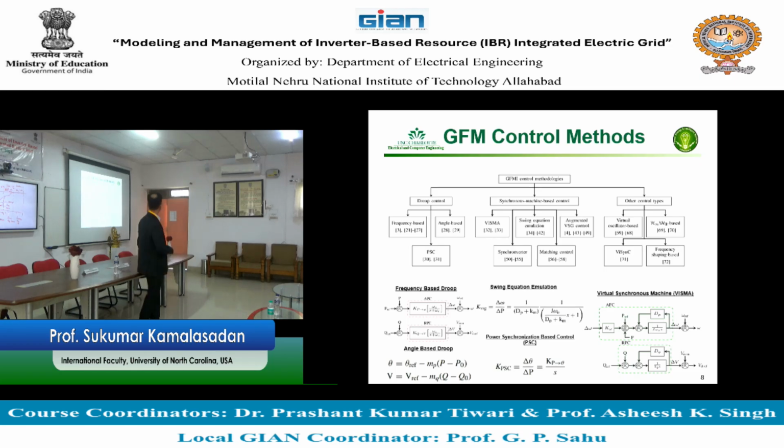So I may have these references, which I can provide to you if you wanted to look at them. But at the end of the day, what is the goal? To get the voltage and the angle, and have the inverter operate much like a synchronous generator, which makes the system stable. That's the whole goal.